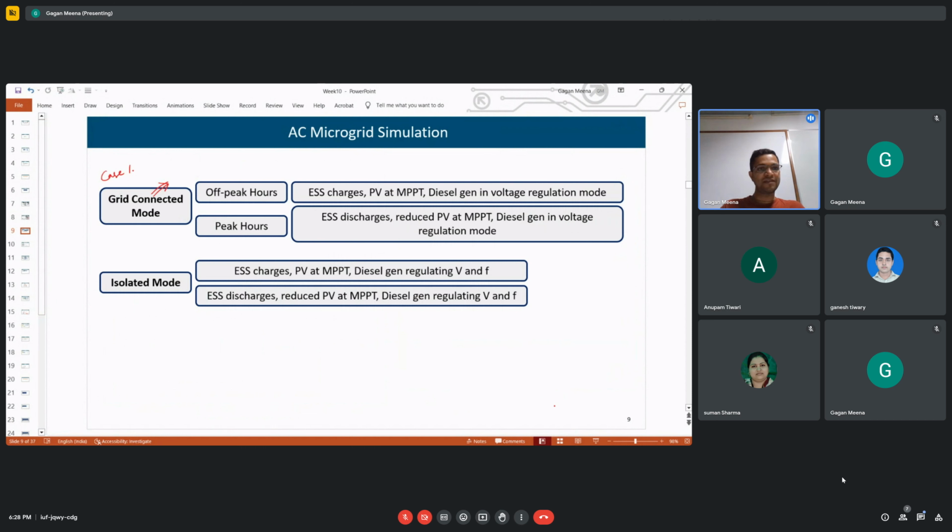Can you tell some limitations of these passive filters? They are fixed. Correct. So even if we provide number of steps, those number of steps are fixed. If the system changes, they are not adaptable. They are not adaptable to varying system conditions due to their size and tuned frequency. They are tuned for a particular frequency, so that we cannot change once installed. So change in system frequency will detune the filter and it will cause increased distortion.